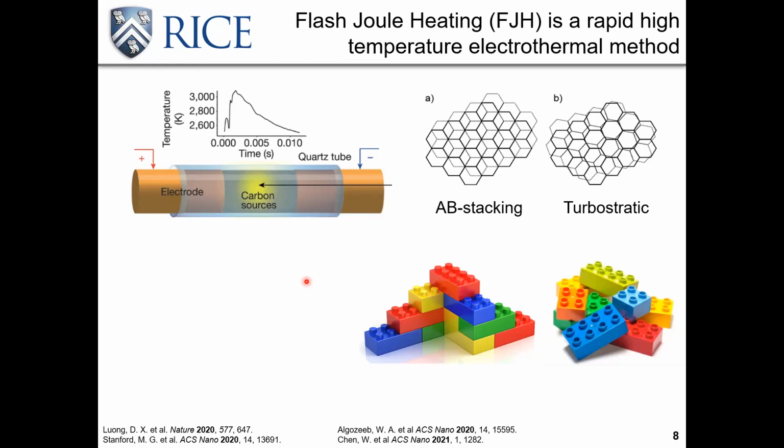To make sure the material can be coated, we use a turbostratic material. Compared with the well-aligned material as shown here, like graphene with AB stacking, the turbostratic material has a misaligned layer structure and weaker interaction, so it can be mechanically exfoliated.